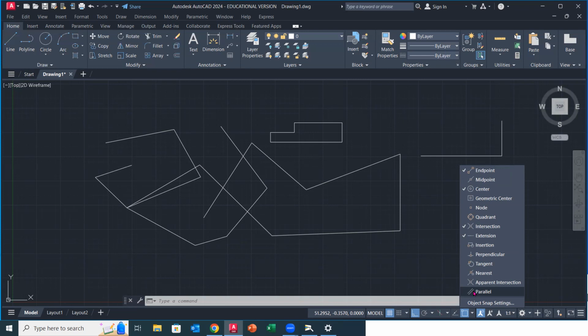Okay. So to ensure that it snaps, this is why they're called object snaps, that it snaps and grabs endpoints, midpoints, centers, we can activate those so that in the background, they're always looking for those. And then that way, we're ensured those. Now, you might say, well, why don't I put every single one on? Because we're going to notice that then whatever you're closest to, it's going to snap to, and it's going to get annoying because it's almost going to be too many. Okay. So you kind of strategically pick the ones that you use most.